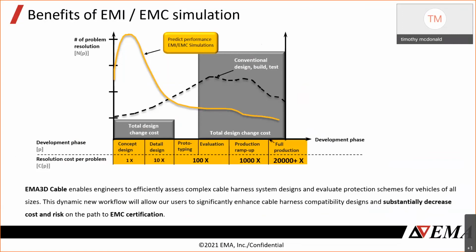All right, and we received 2 more questions, or 3 more. The first one's from Tapesh. Is there any limitation in terms of the PCB file extension that is supported by the software, such as ODB++? Yeah, so SpaceClaim has added in R1 earlier this year ECAD imports, so we can import many types of ECAD directly.